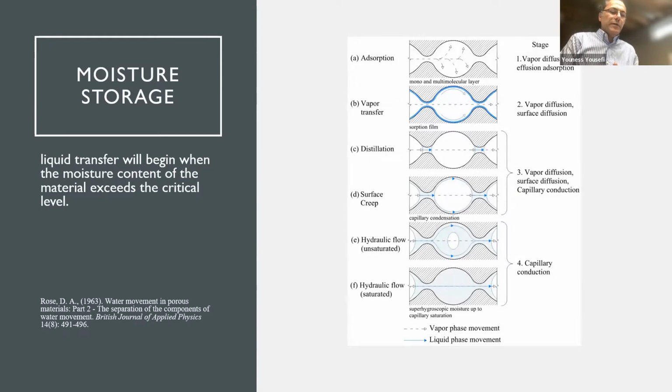When the relative humidity goes high, similar to a place like Vancouver, the concentration of vapor molecules goes high, and it causes vapor to be adsorbed as layers on the surfaces of the pores of the material. It goes higher and higher with more layers, and starts to be like liquid phases, which is associated with moisture transfer through the material.